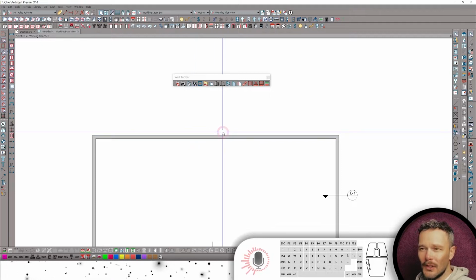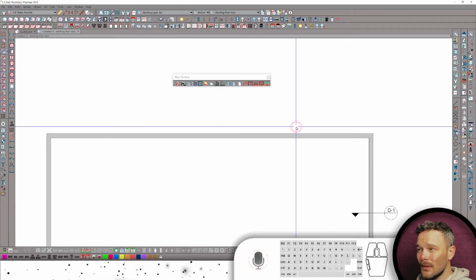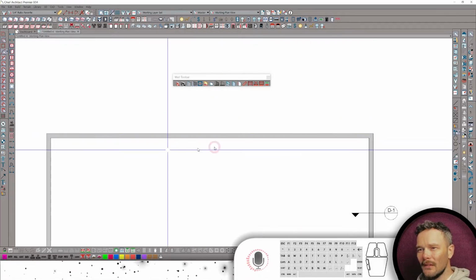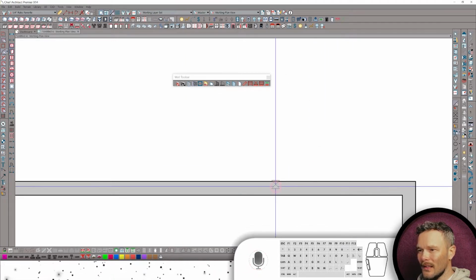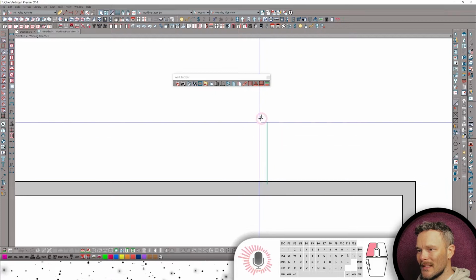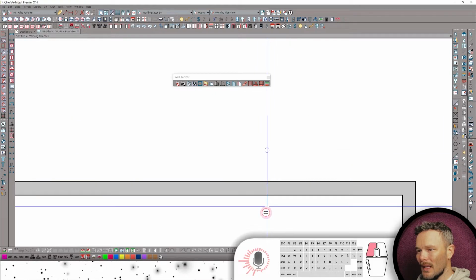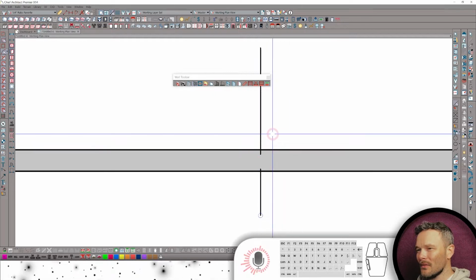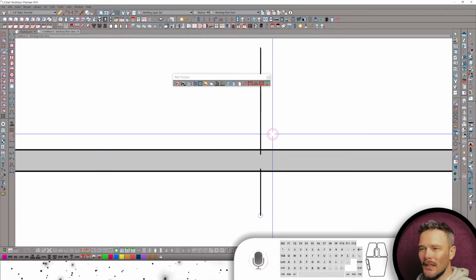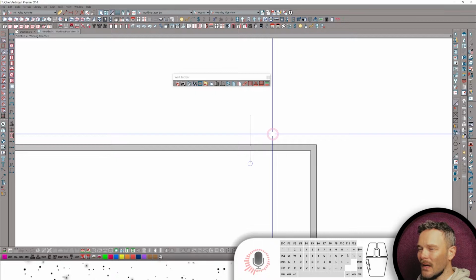I do not show layers, even though show layers is checked. Everything looks like one solid item. If we draw a line, you'll see that I actually do get to snap to that main layer, even though that main layer looks like it's invisible. It is there. This is just a preference for me. It's a very clean look, so on a print set, it looks very clean.